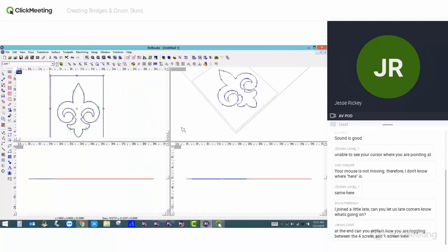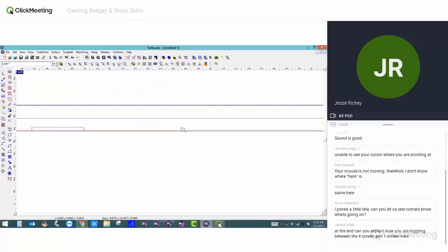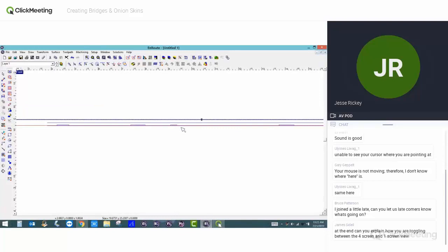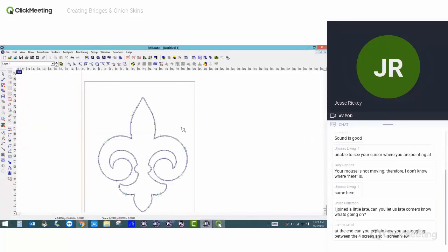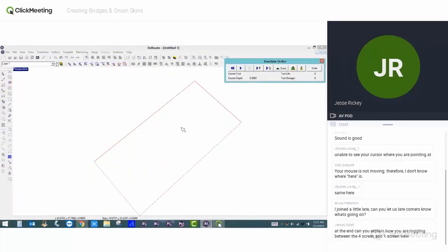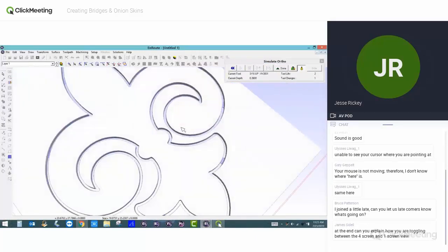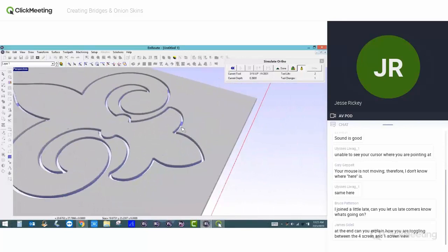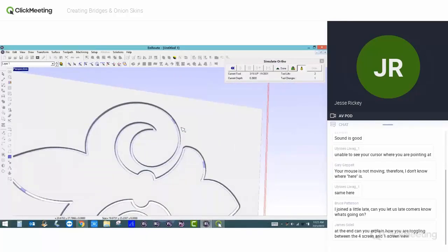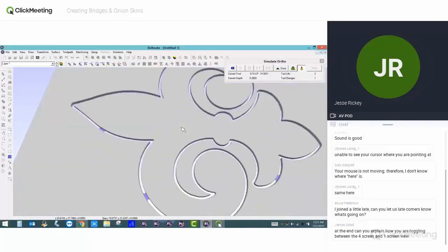Once again, I'm going to go ahead and double check it here. Okay, my parts are inside, which is good. And if I highlight this and view it in 3D, okay, I can see that it is cut out in the majority of the areas except for where we have those bridges, and you see just those little bitty tabs inside here as well.